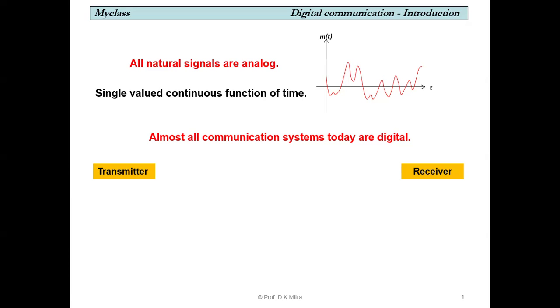But today in a digital system, there is a transmitter on one end and a receiver on the other end, and a series of pulses flows through. The pulses are actually voltage pulses, and pulse height can be 5 volt, 10 volt, 3 volt, anything as per the design. For convenience, when there is a pulse, we call it binary 1. When there is no pulse, we call it binary 0. So we also call it 1001, something like that. But actually, they are voltage pulses.